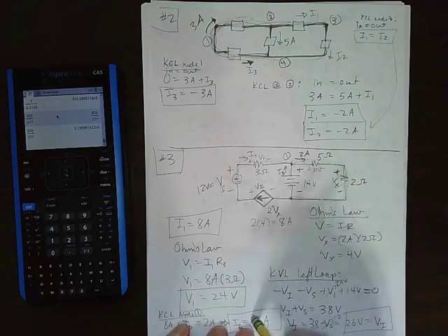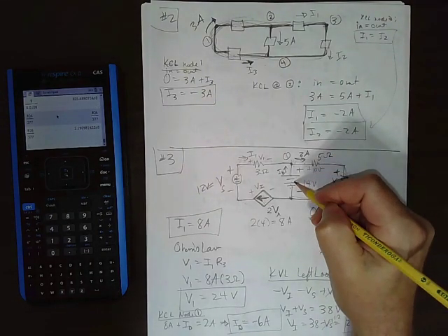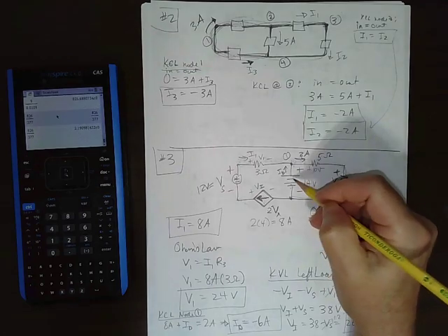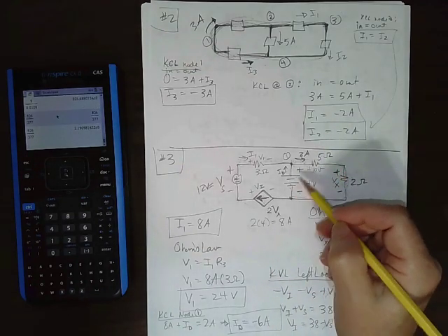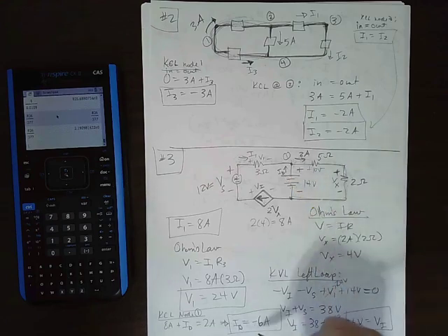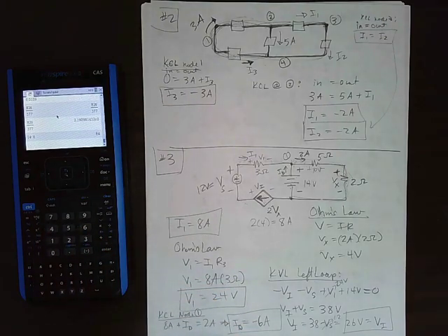So it's not actually producing power, it's absorbing power, because it's got a negative current. If we want to calculate the power of a source, we do power equals VI, so power would be 14 times negative 6. What is 14 times 6? Taking in 84 watts, right?